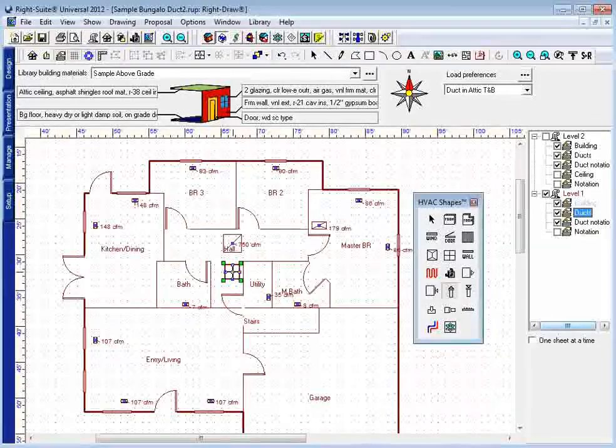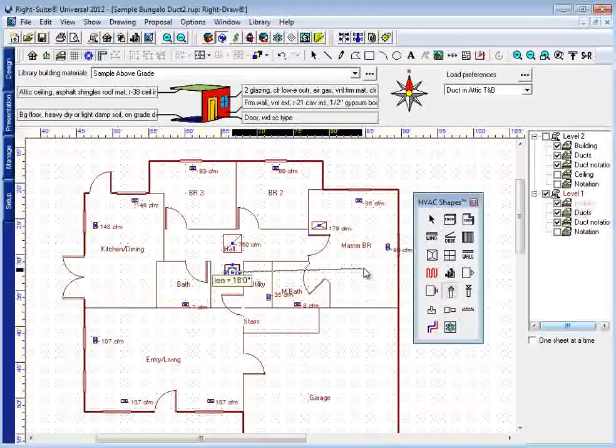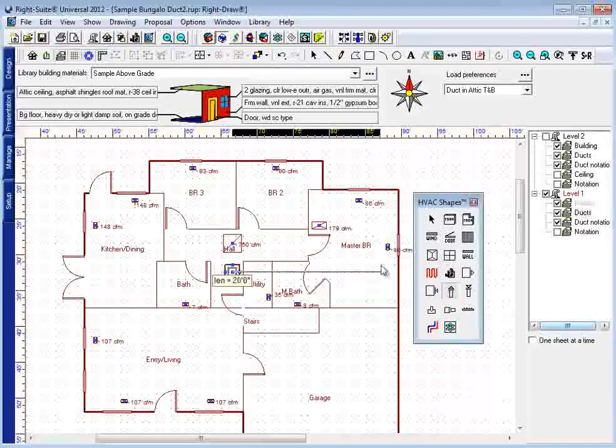Starting here in this middle, I'm going to left click and hold, and I'm going to drag a line. Now, you see how sometimes that line can come off a little bit crooked? Especially with lower snap settings, this can happen. If you hold the Shift key, that will maintain a straighter line when you draw it.